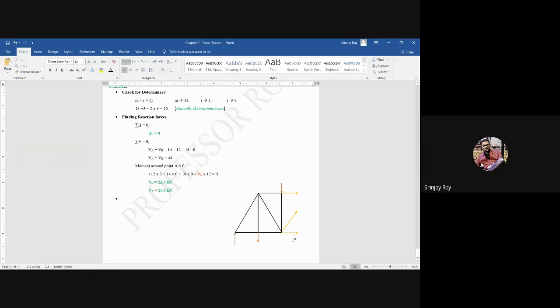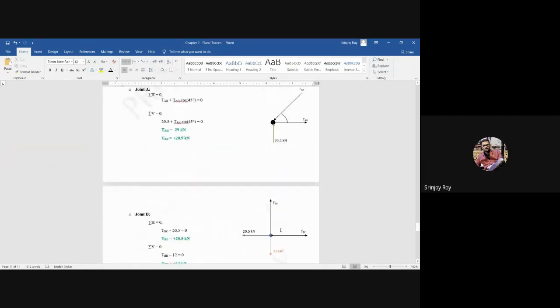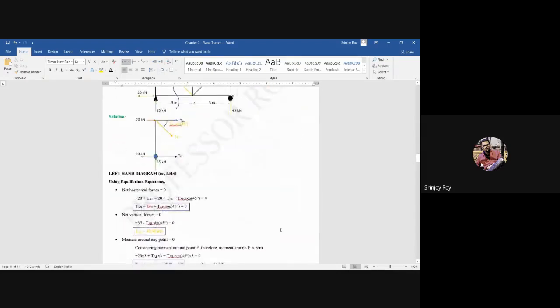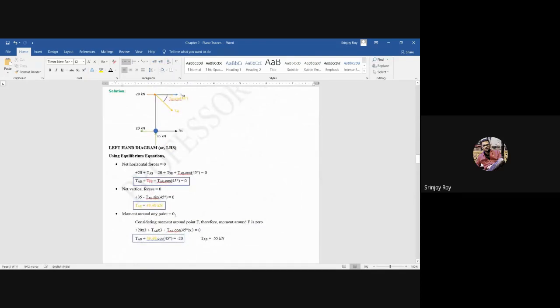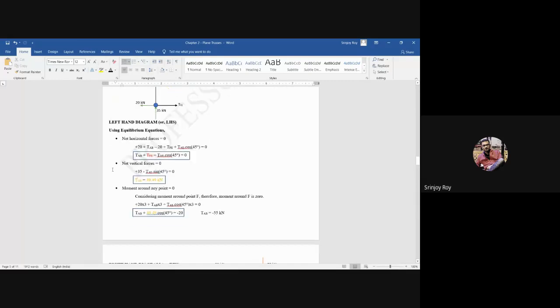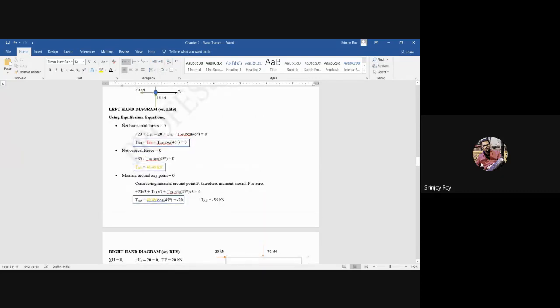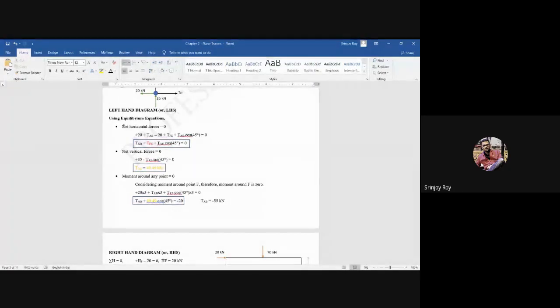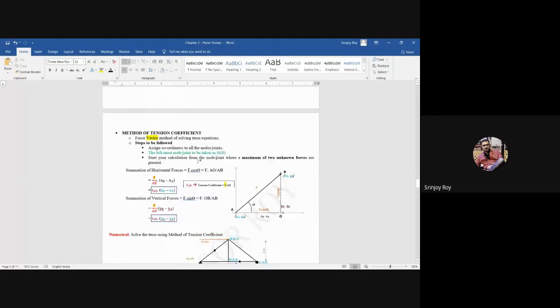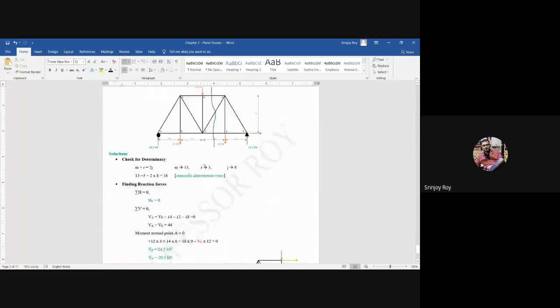Now what we have to do over here is, देखो method of sections में कैसे solve करते हैं, याद करके देख लो. Method of sections में how is it solved? ये देख लो. Equilibrium equations में क्या? All these things. Net horizontal forces will be 0. Net vertical forces will be 0, and the moment around any point will be 0. Yes or no? These three equations are actually just required. Same thing. Horizontal force is 0, vertical force is 0. So these three factors will be coming into consideration like always over here. So let's do it together. Okay, fine.